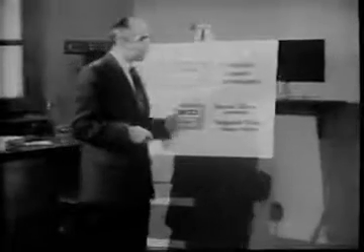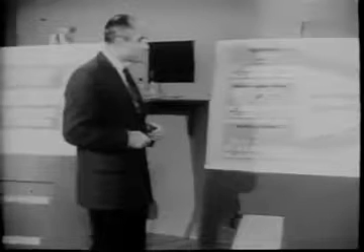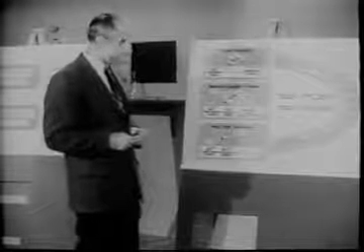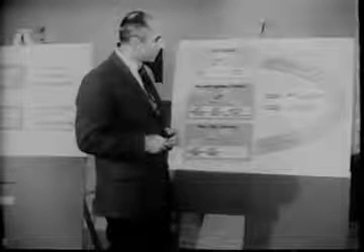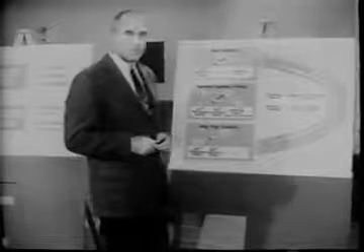Then, by thinking about two extreme cases, fluids of very small viscosity and fluids of very large viscosity, we were led to a most useful idea, the Reynolds number, which allows us to categorize the type of flow in terms of the relative importance of viscosity. Finally, we recognized that the drag on an object, like the forces on a fluid particle, could be divided into two parts, pressure drag and viscous drag. This set of ideas is a powerful tool for interpreting and explaining experimental observations.